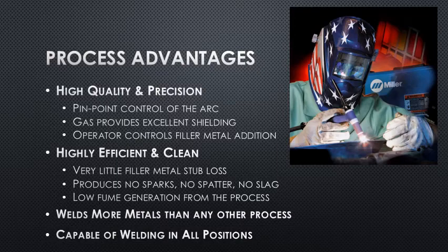TIG is also very capable. It welds more metals than any other process. In fact, it can achieve high quality, even X-ray quality welds on almost every material out there that's weldable. And it's capable of welding in all positions, so it's extremely versatile.